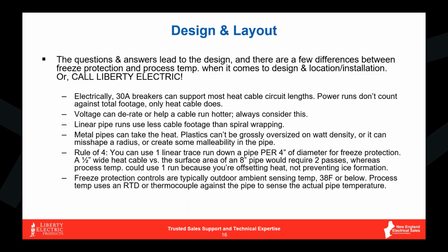Big one being 30 amp breakers. If you can power these circuits with 30 amp breakers, that's really going to behoove you with less circuits overall, and you can get the most amount of heating cable on that circuit length. So it's definitely the best value, as far as your supply breaker size.